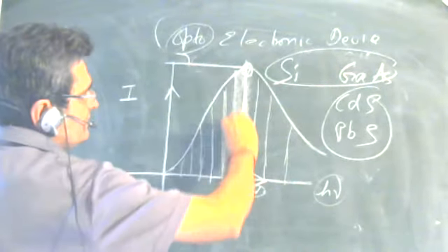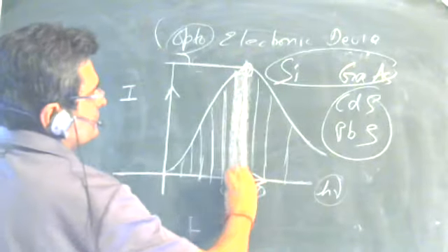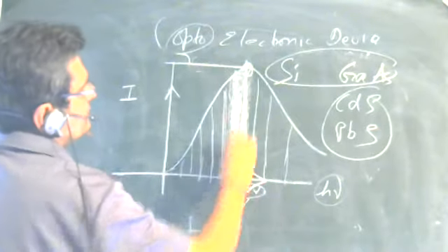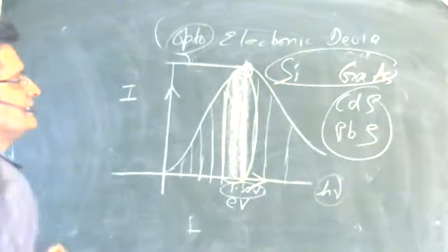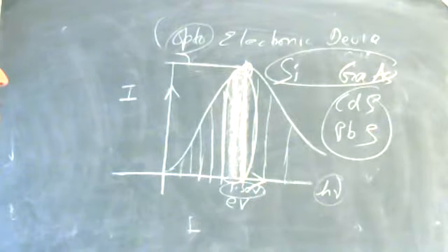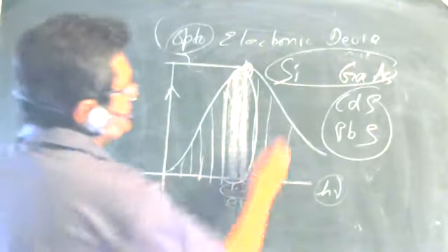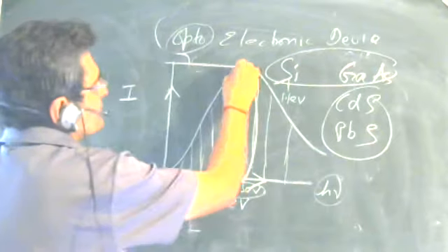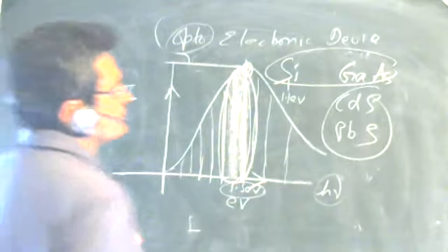So if we are able to exploit this region around 1.5 electron volt or less than that, then we are able to utilize most of the intensity. So the utilization of solar radiation is more optimal. That is why silicon, which has 1.1 electron volt, is preferred, because you are able to exploit greater intensity of solar radiation.